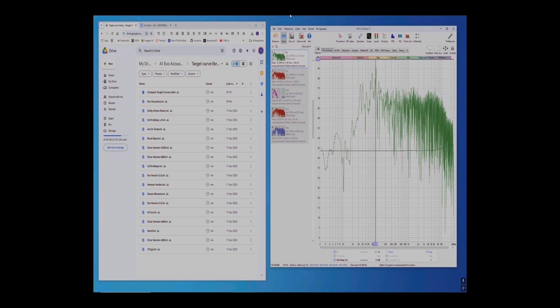What else? Acoustica is capable of hacking the 6 meter maximum distance limit in Denon Marantz receivers. You can use up to 7.35, but there is a trick with that. If your calibration optimization use the limit higher than 6 meters, it will work, but only until you go in the setup menu and try to edit distance settings. If you try to edit them, then it's gonna cap them back to 6 meters. So if you get a warning during optimization that Acoustica is using a higher limit than normal for your system, then do not go and edit speaker distances in your receiver.